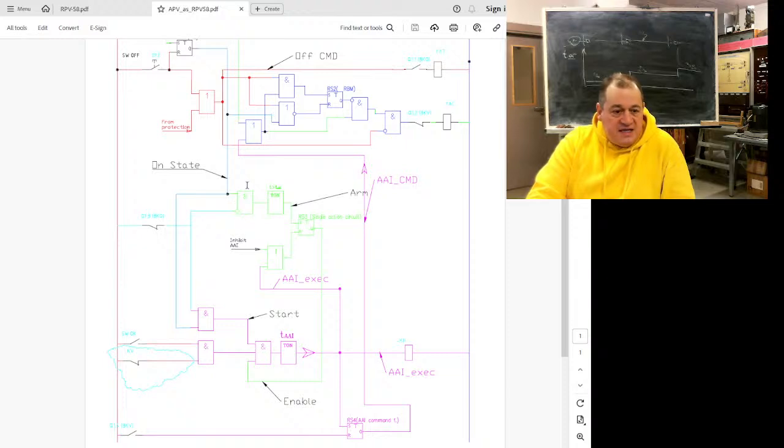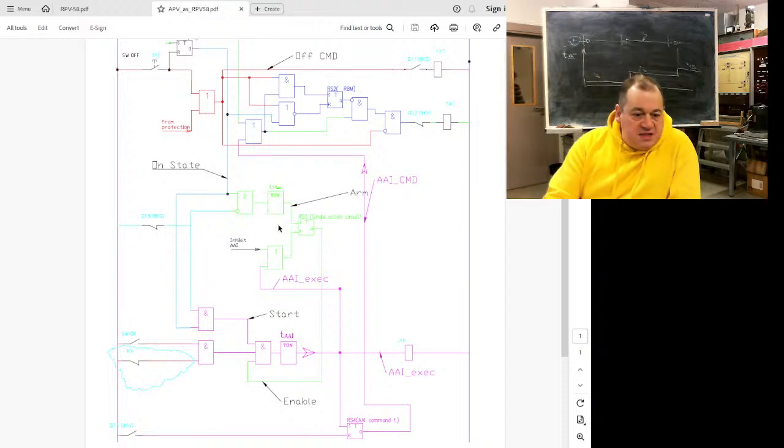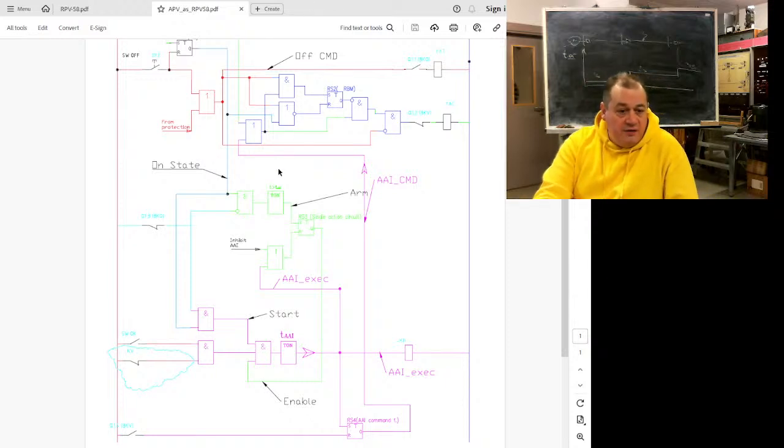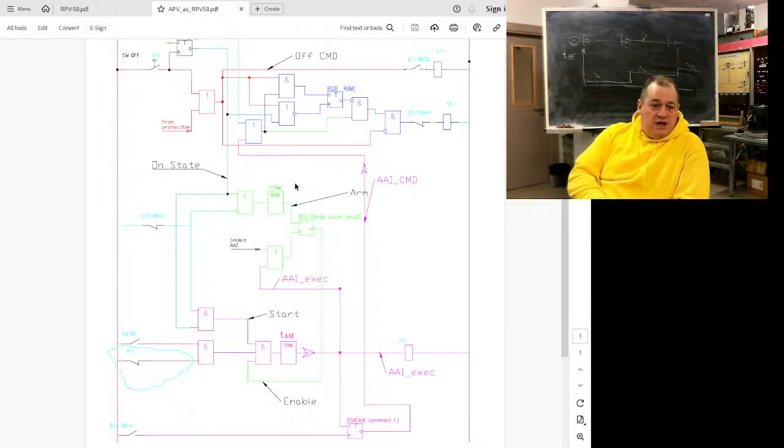The state of the circuit breaker is compared with the last sent command in 2 ways. Here, this circuit with its protective timer. This green circuit I painted green, it's a single action circuit. It allows reclosing only once. Some models allow 2 or 3. They had not only a timer but a counter. Anyway, in our case, this circuit allows operation of reclosing only if the switch remained in on state approximately a minute. Otherwise, it will not pass the reclosing command.